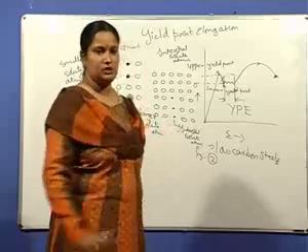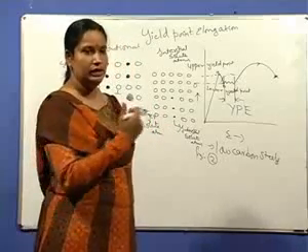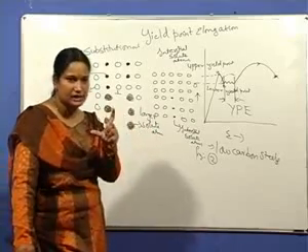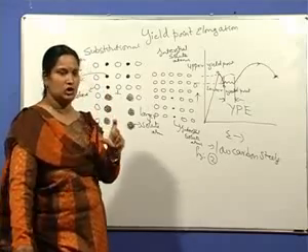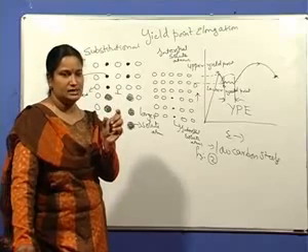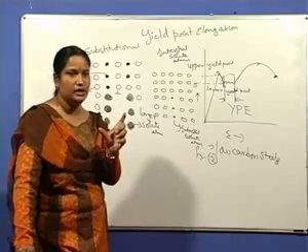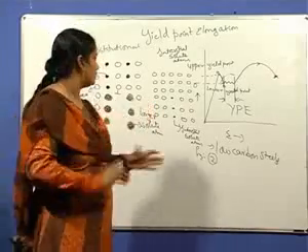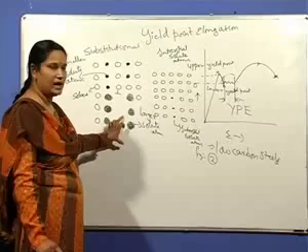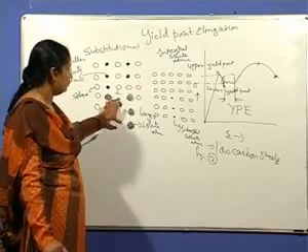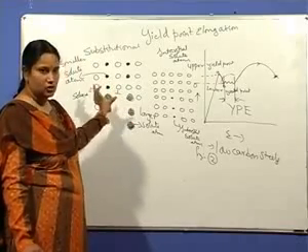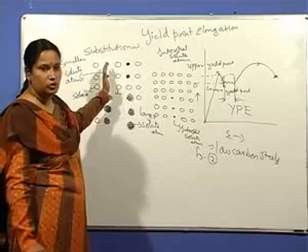So if you are able to understand these figures, it will be much more clear to you. Substitutional are two types. Substitutional, that means the solute atom is slightly larger than solvent or slightly smaller than solvent. If it is slightly smaller, it results in contraction of the lattice. If the solute atom is slightly larger than the solvent, it results in expansion of the lattice. So below the edge dislocation, where the lattice is expanded, larger solute atoms occupy the positions. Above the edge dislocation, where the lattice contraction takes place, the smaller solute atoms occupy the positions.